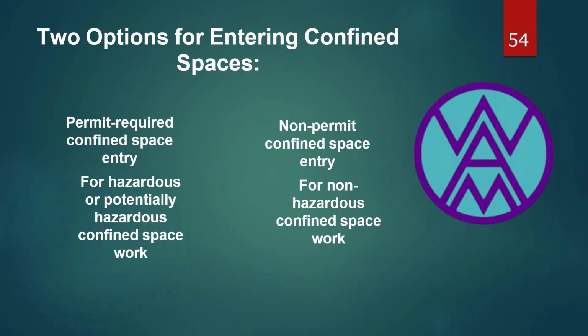Yeah, sure. Okay, so you have discussed three kinds of permit. One is the cold work permit, like when a person is applying paint or trying to change a switch or electrical equipment. He uses a cold work permit over the LOTO. The second you told me about is the hot work permit, like when this person is working with a welding machine or any machine that ignites, that produces heat, that will be a hot work permit. But when a person is working in such an area where there is a possibility that he gets suffocated due to the lack of oxygen, or breathes toxic gas that can lead to death, or a machine engulfs or crushes him, due to some miscalculation, if someone didn't know that a person is working inside that confined space and starts the machine, in those places we can use the confined space permit. Is it clear?